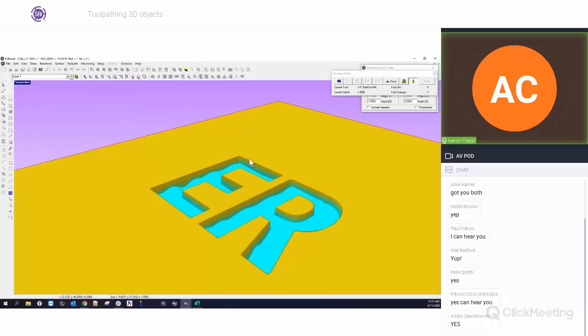It's really easy. It sometimes can be a little bit tricky when you're thinking about different layers and things like that, but it kind of helps give you some unique effects. And that's how we would recommend putting letters on top of any kind of textured relief if you want them to be flat. Now, if you want those letters to carry the relief with them, then you might have to use the add feature and things like that. So there's different ways, but if all you want those letters to do is stand up straight out of the texture, this is the way to do that using masking.